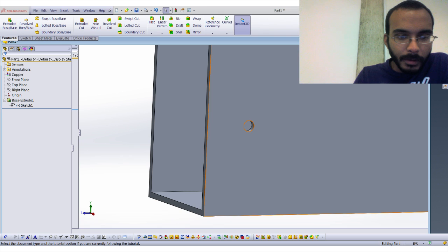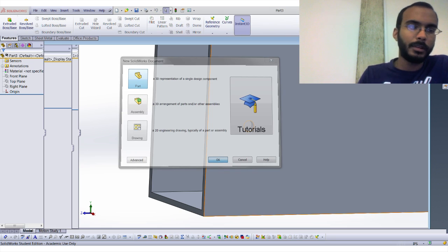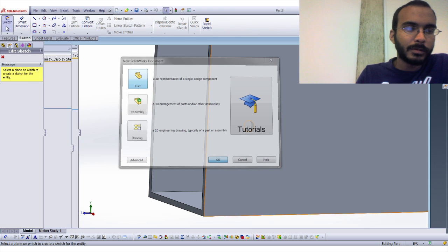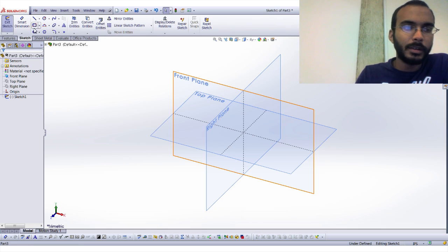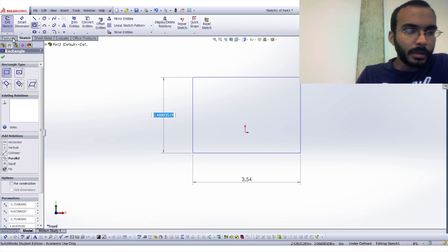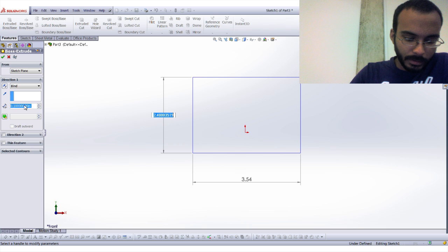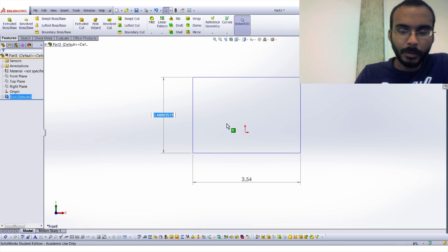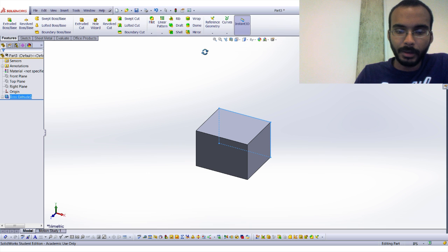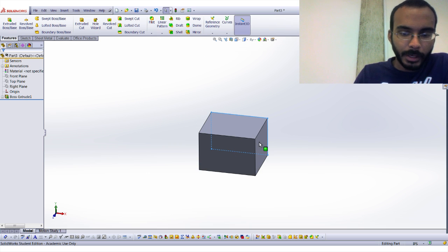All right, so repetition helps everybody learn. Part new. You can click over on sketch, we're going to hit the sketch button. That's how we create sketches on the front plane. We can make a 2D rectangle again. We can go to Features and Extrude Boss, and we can tell it whatever size we want. And when we check, we're back to having a rectangular prism.